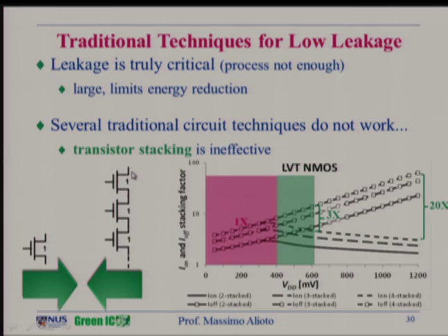the effect of stacking is reducing leakage significantly, at least at nominal voltage. So at nominal voltage, and this curve refers to 2, 3, 4 transistors, basically the leakage compared to the single transistor is reduced by a factor of 10 or even more, so by a few tens, by a lot. At the same time, the I-on current for 2, 3, 4 transistors is not reduced as much. It's reduced by a factor of 2, 3, less than 4. So in this case, stacking is very effective because it's reducing leakage significantly, but it's not reducing I-on, so it's not degrading performance significantly.